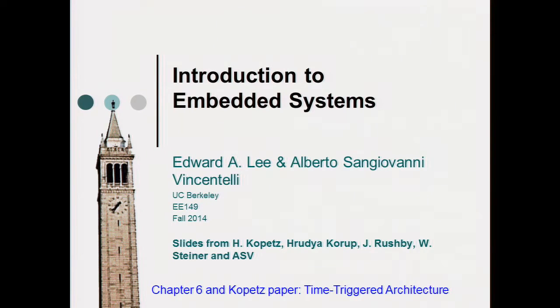Then you write the register, the clock comes in, you transfer data into the output buffer, and then you read the data. This guarantees that you have no races, as long as the computation is within the clock cycle. This is rather simple, and it is a very well-known mechanism. Everybody plus his brother uses it.